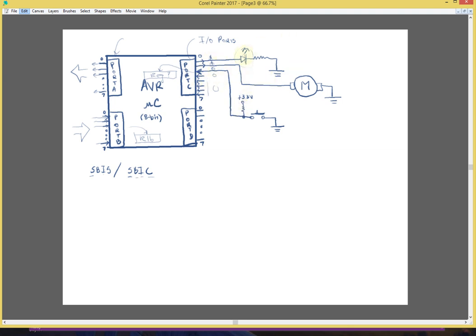And then based on that, I want to turn the light on. So let's look at what that code would look like. Actually, I don't need to read anything. I want to turn the light on if the switch is 0, and I want to not do anything if it's 1. So I want to skip the next instruction. So I'm going to say skip the next instruction if the bit is set on pin C. Again, I'm reading input bits, not output pins.